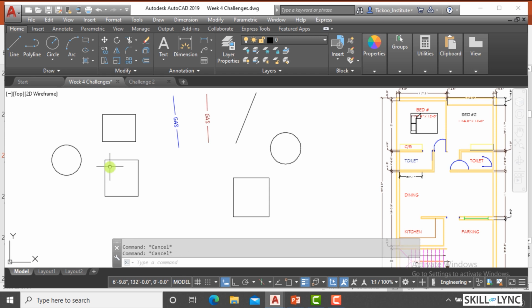So if you want to do some modification, let's say I want to copy the last object created, I say copy, L, and you can copy this. Now if you say CO for copy and say P for previous, obviously the last object created was this rectangle, while the previous object selected was this object. So this is the concept of P and L.